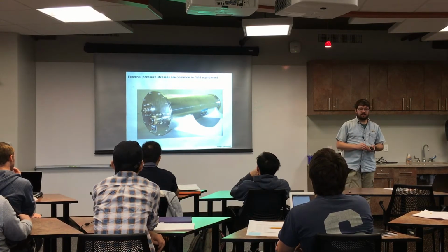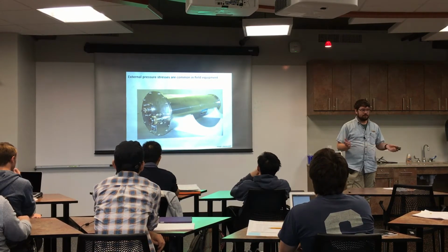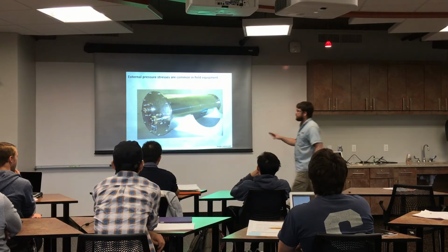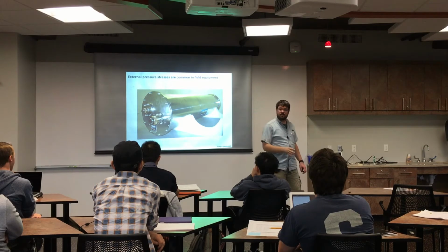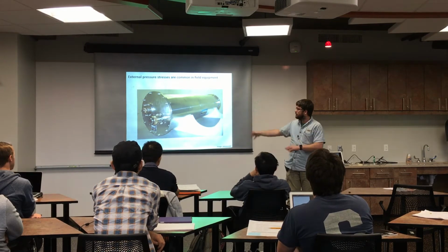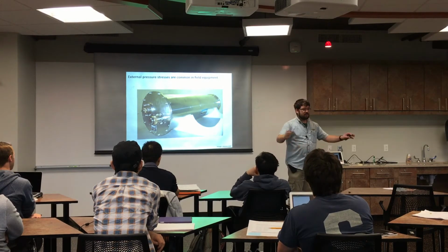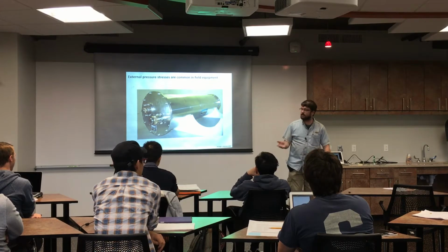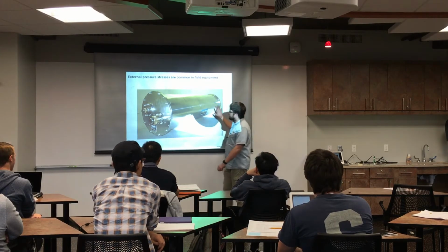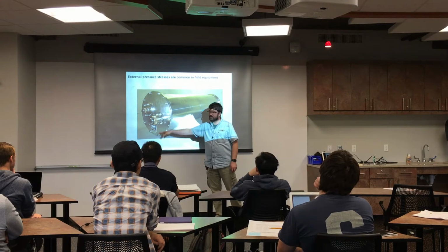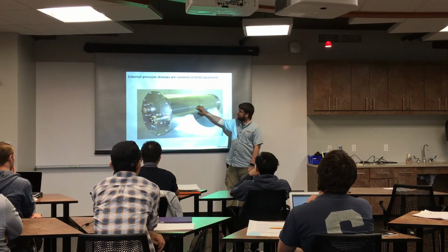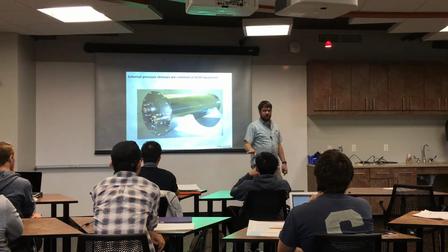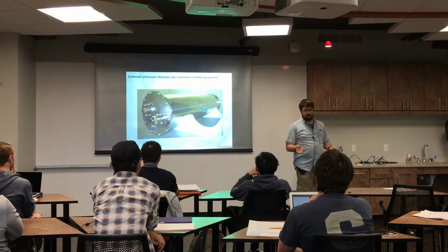External pressures seem like the same story because you just have pressure, except now the pressure's on the outside of the vessel. This would be something that would house subsea electronics. So you would put your circuit boards in there, for whatever goes on the outside of a submersible to do some study, let's say, and submerge it. So you want to keep all the electronics dry, but have some connections to them. Now the pressure's on the outside, you have atmospheric pressure on the inside possibly. And there's a lot of different design considerations you have to use for internal versus external pressure, believe it or not.